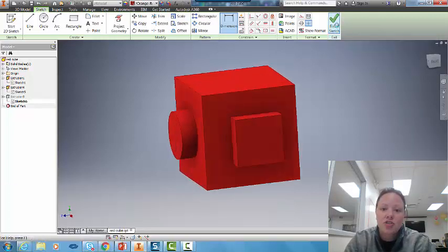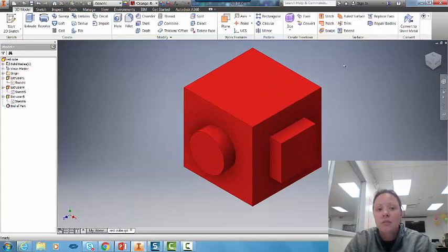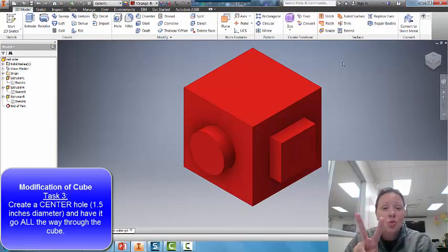I'm going to finish my sketch, and it made the adjustment. So there we've already centered 2 of our extrusions. And all it takes is to constrain the dimensions from one edge to the part that we're trying to adjust.